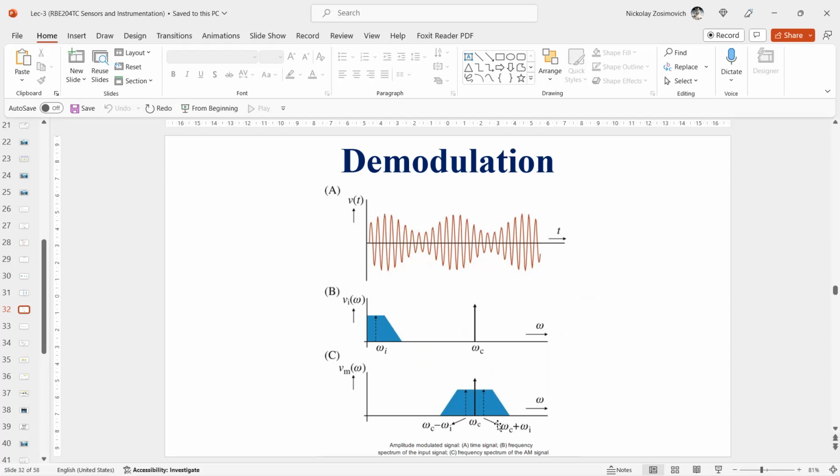And this means that envelope detectors operate only for AM signals with carrier. In an AM signal without carrier, the envelope is not a copy of the input anymore. Moreover, additional information is required with respect to the phase of the input for full recovery of the original waveform. An excellent method to solve this problem, and which has a number of additional advantages, is synchronous detection.